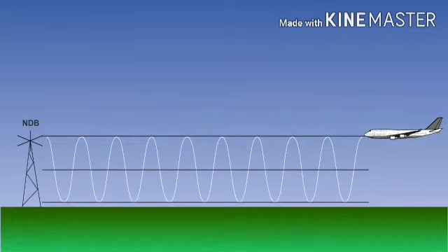If the carrier wave were unmodulated, it would simply be a radio wave at a constant amplitude and frequency. This type of signal is ideal for direction-finding equipment such as the Automatic Direction Finder, ADF. Its waveform would look like this. If the carrier wave were transmitted at a frequency in the audible range, one would hear a continuous tone, like this. Radio signals are designated according to their characteristics. The unmodulated carrier wave is designated N0N.